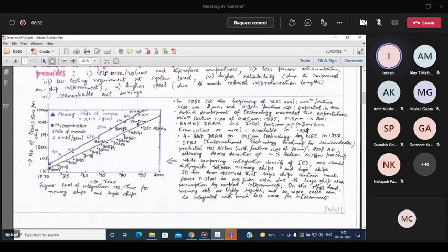Later on, arithmetic co-processors were brought in, and then for the digital signal processor, components like MAC, that is multiplier and accumulator, a shifter, and various forms of parallel multiplier were incorporated in the particular silicon wafer. That led to some irregularity in the placement of different logic units, and the interconnection complexity grew.